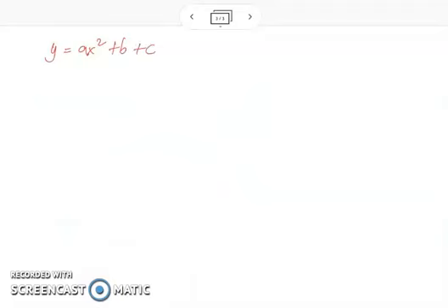The lowest point that we are referring to has an elevation of 270, equal to 0.00102 times 122.5 squared. This is the value for x, the distance of the lowest point from PVC.